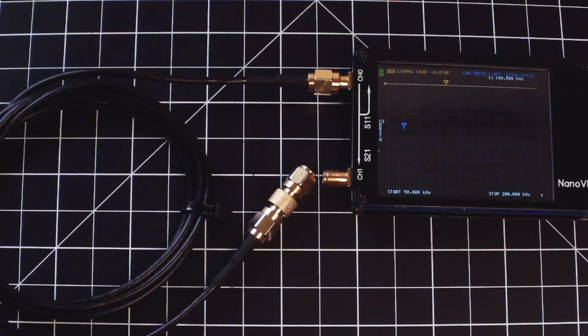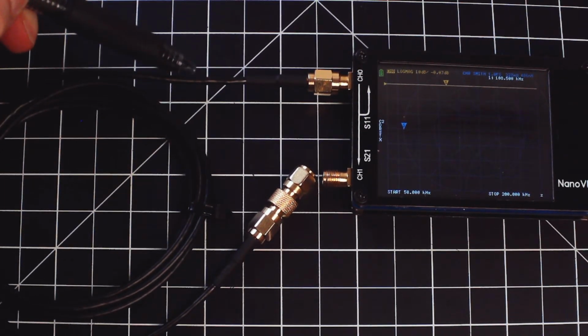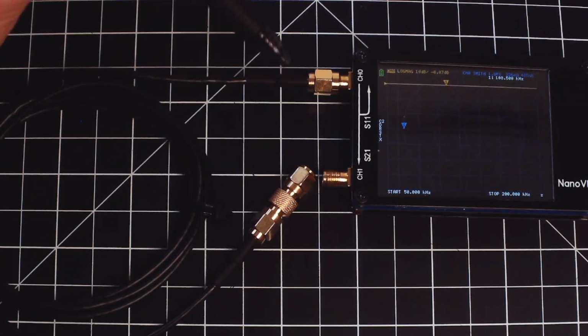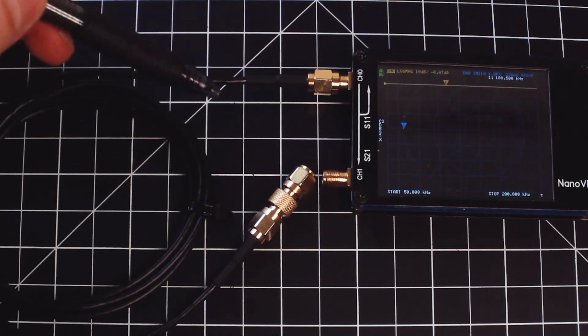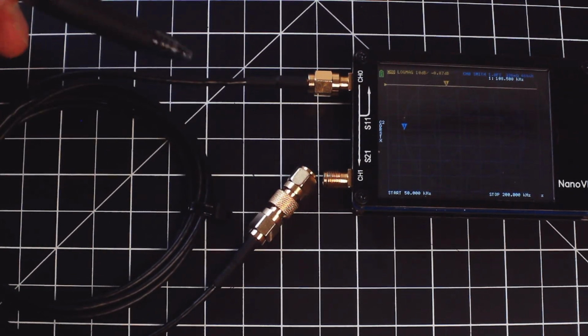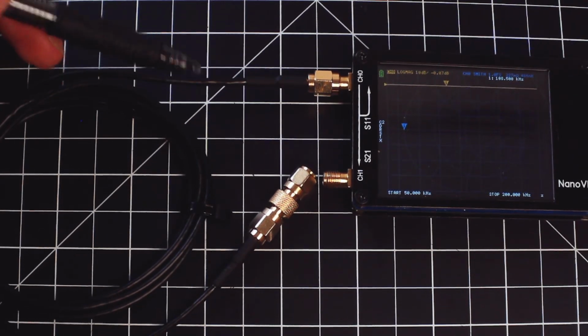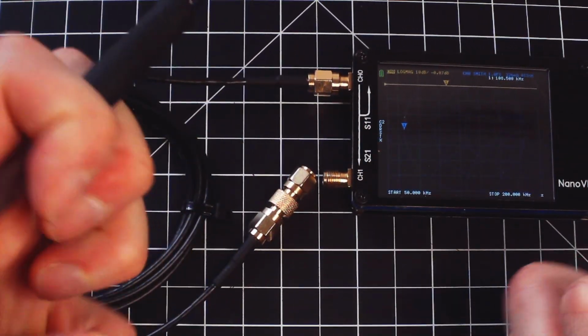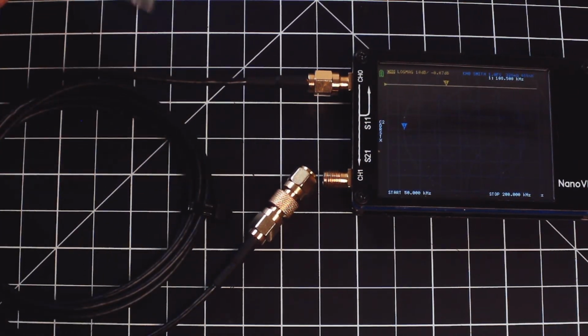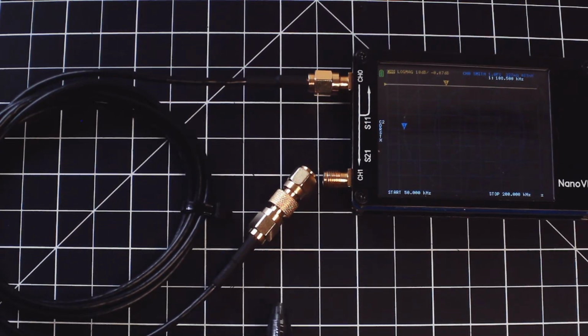So the reason for that is actually the skin effect. That is, at low frequency, the current inside the conductors wants to flow throughout the entire volume of the copper on the inner conductor and on the shield. When you go to higher frequency, that current then gets squished to the outer edges of all the conductors, which actually manifests as a reduction in the inductance. So yes, this is technically an accurate measurement of inductance, but you cannot trust it at higher frequencies because it will in fact physically change.